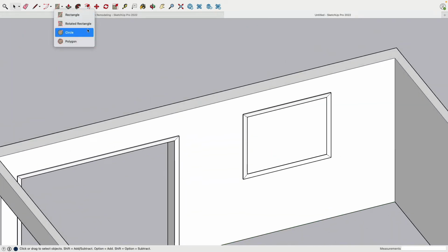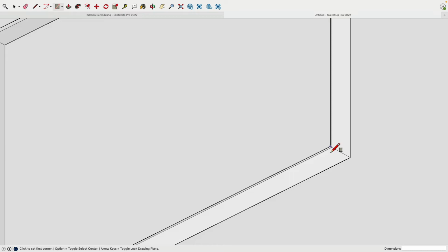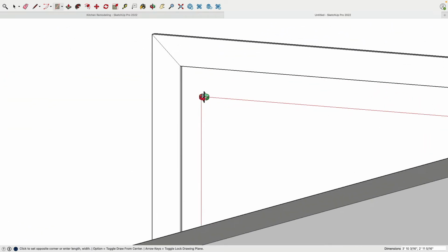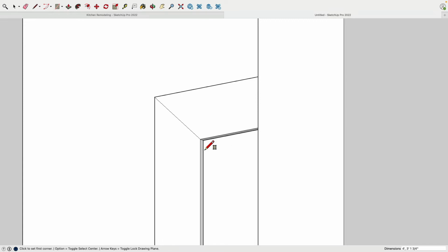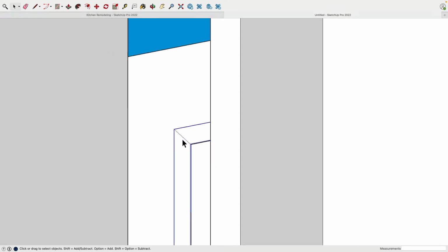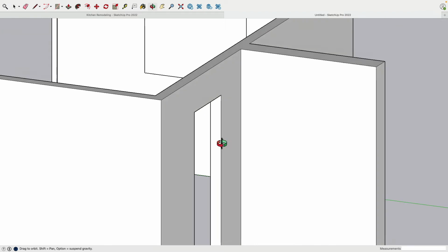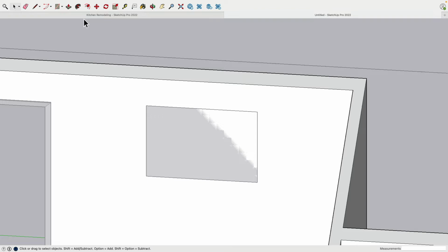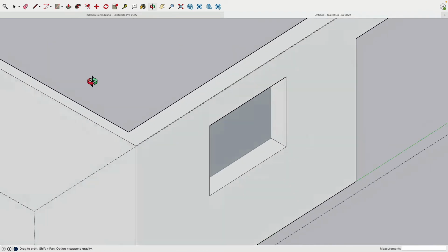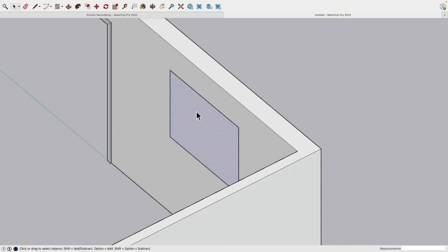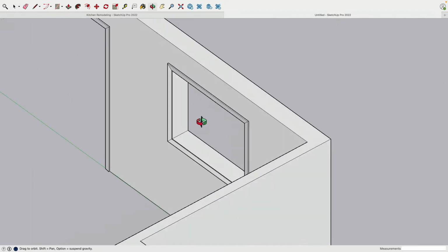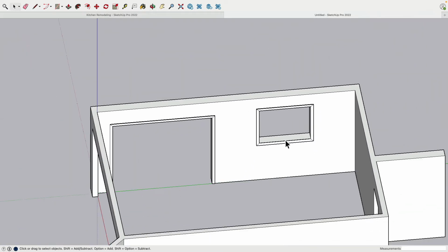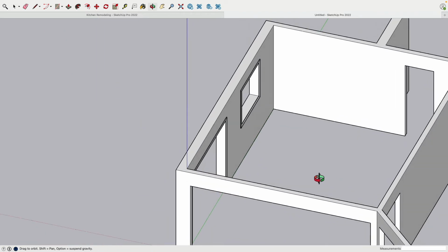So you see now there is another snap target, simply to put in the opening for our window, which I did on the outside wall, so that was kind of silly. But I can still use it. I just hit the frame, triple click into edit group for the wall, and then we just redraw the rectangle one more time, snap to there. Yep, it went through, exit the group, and this whole thing we delete there, and then we show everything. Cool. Okay. You see?